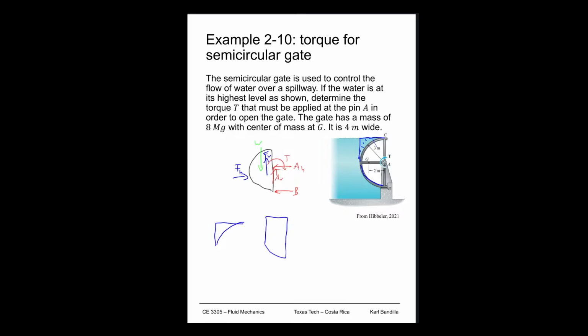And so we know that this part on the left is going to result in our force going upward, and this one was going downward. I'm sorry, because it's sitting on top, this is the one that goes upward. So if we add them together, then basically we can subtract this top one out, and then all we're left with is the volume of water that we have to find, which is exactly the semicircle.